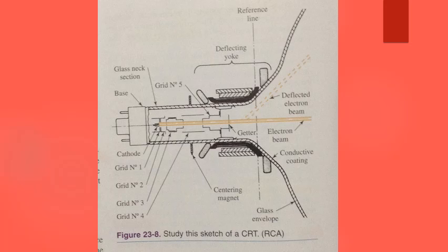Therefore, the screen is bright or white. At cutoff bias, the current is zero and the screen is black. The tube operates at a selected bias on the control grid. This bias can be controlled by the knob on the TV or a button on the TV remote called the brightness control. When no picture is being received on the TV, the scanning electron beam can be seen in the form of lines on the TV screen.